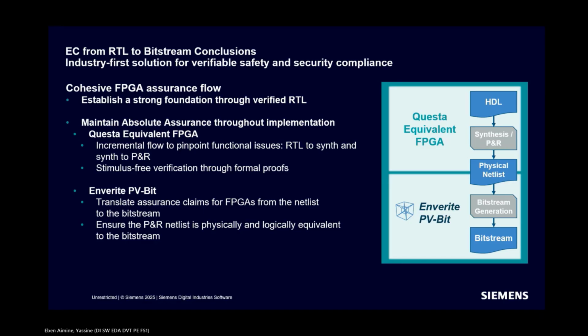So the bitstream checker, would that pass or fail if it's functionally the same, but it's physically moved registers about and changed the routing? No, so with the bitstream, that's relying on the location on the device and what type of device it is. So if it's a different placement, it will fail. Yes.